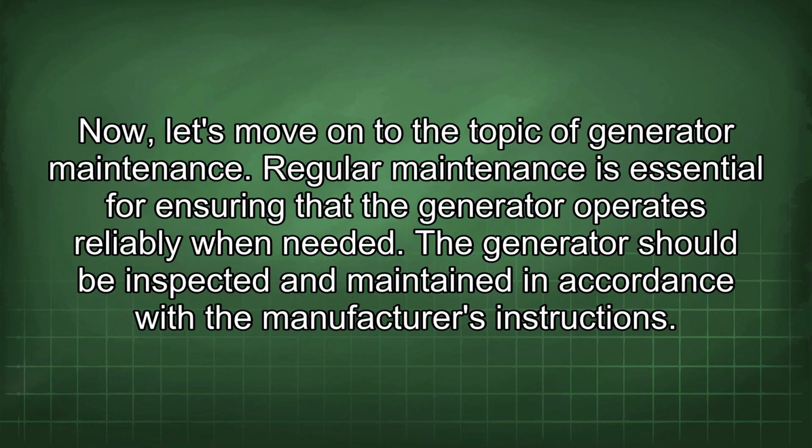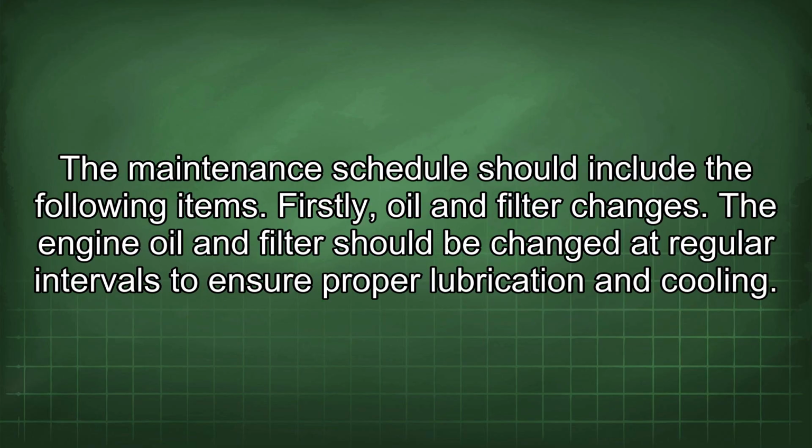Now, let's move on to the topic of generator maintenance. Regular maintenance is essential for ensuring that the generator operates reliably when needed. The generator should be inspected and maintained in accordance with the manufacturer's instructions. The maintenance schedule should include the following items. Firstly, oil and filter changes. The engine oil and filter should be changed at regular intervals to ensure proper lubrication and cooling.